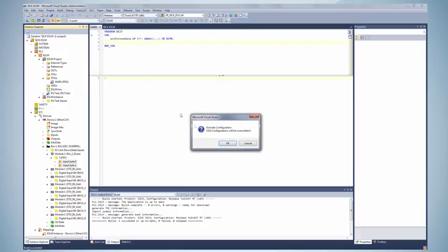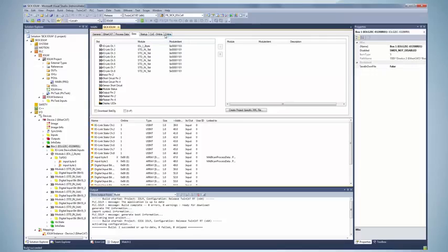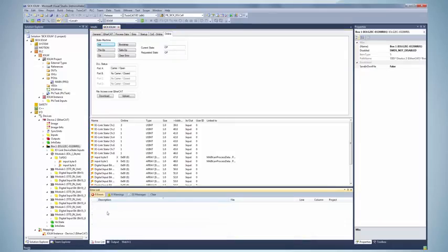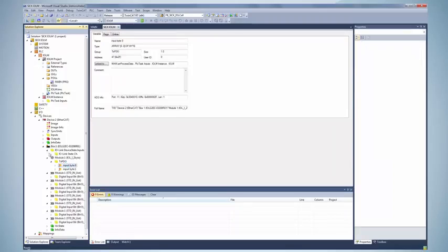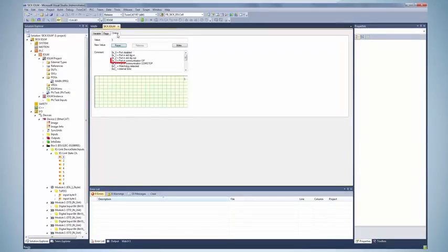Then the TwinCAT runtime is started and the connection status of the I/O link master can be displayed and checked. Select the I/O link master and the Online tab. The I/O link master must be in operation status, OP. If this is not the case, the error list will show an error or a warning. For visualization of the connected sensor's process data, click in the hardware tree on the specific port. The current value of the sensor is directly visualized.